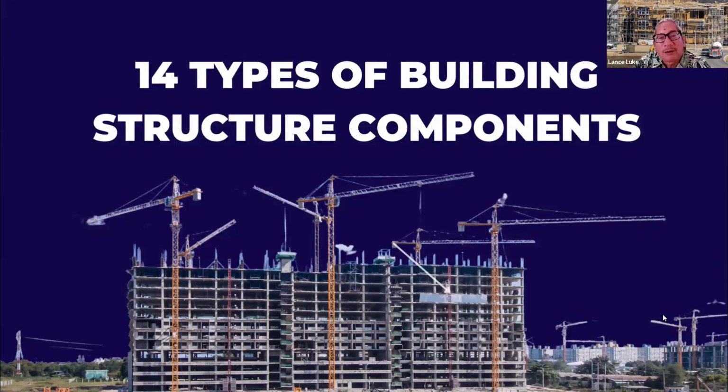And then on the roof, you have what are called purlins, which are horizontal members that support the roof covering. Now, in lieu of the purlins, you could have plyboard roof decking, like on a single family house, or on a large high-rise building it's normally concrete. Okay. And then there are two other components, which is a lintel.